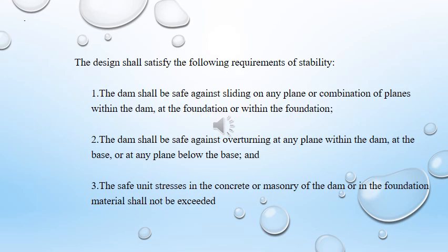The design shall satisfy the following requirements of stability. The dam shall be safe against sliding on any plane or combination of planes within the dam, at the foundation or within the foundation.